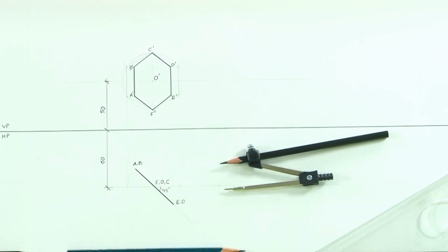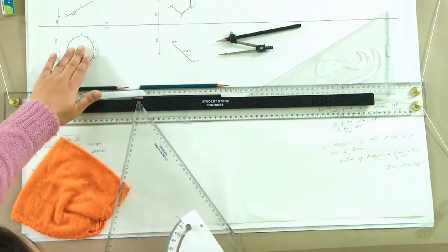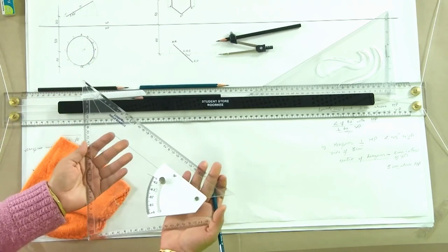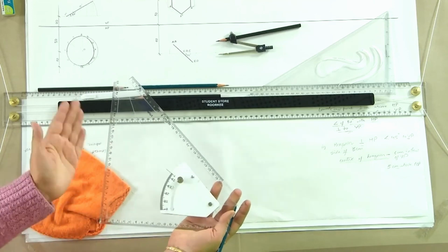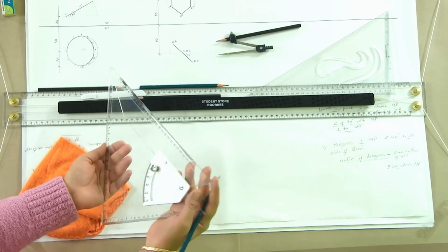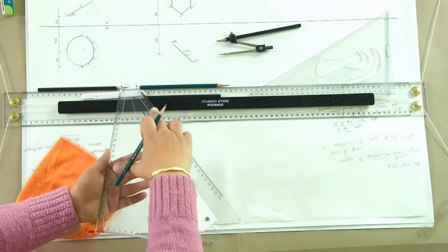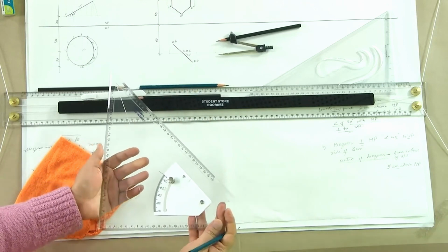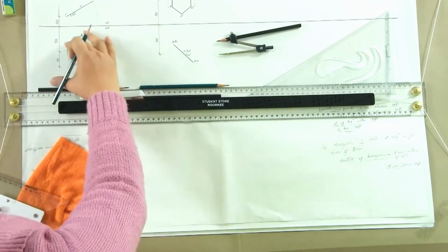Now, if you also see in this case, since it is being inclined only in one direction, the lines which are remaining parallel to the reference plane, for example, in this case the circle, suppose we have this as a circle and it was originally parallel to the HP. Now, as we incline it, assume that each of these lines in the circle is still there. In that case, the line will still be seen as the same length, which is what is happening. The horizontal trace remains the same.